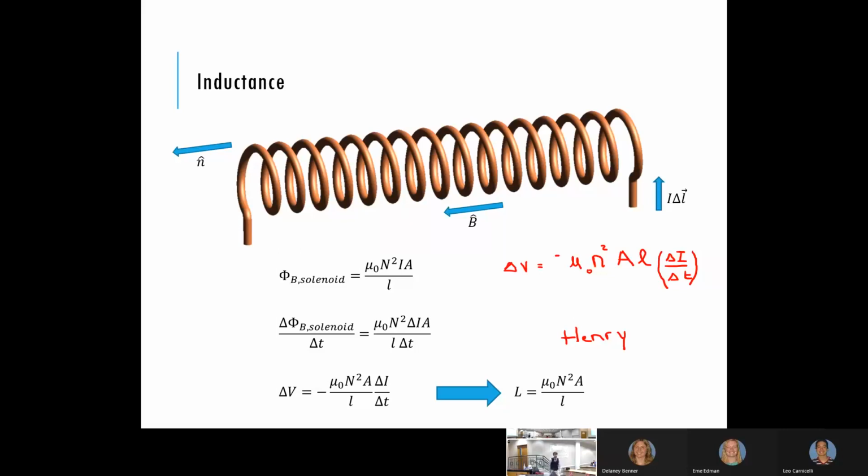From a manufacturing standpoint, inductors are more expensive because you have to include more copper. Copper is more expensive than, say, aluminum. You can make capacitors out of aluminum plates. You just need a metal. Whereas with an inductor, you need to actually run the current through, so you tend to go with copper, so it tends to be a little heavier. So there are all these extra considerations. But yes, that's one of the advantages: inductors can smooth over these rapidly changing currents.